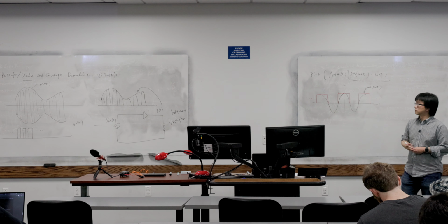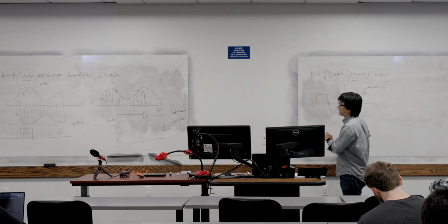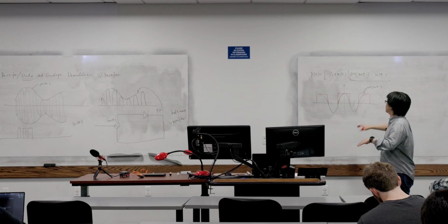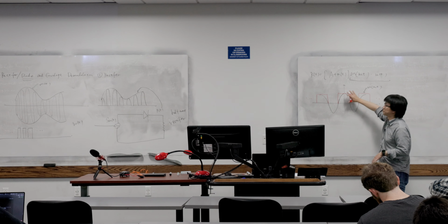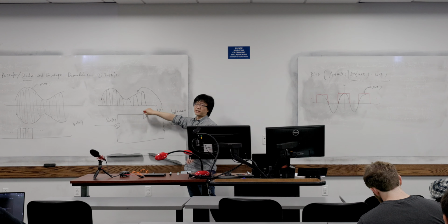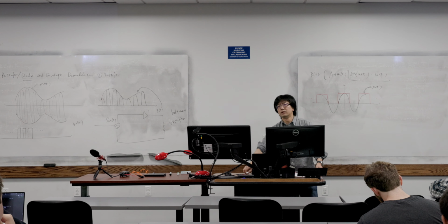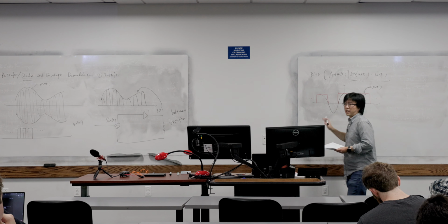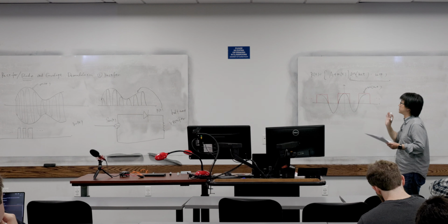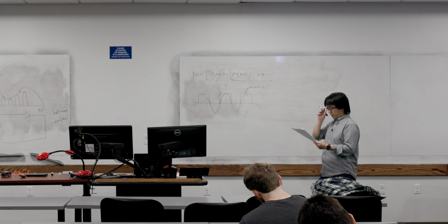Right, so this is what we do. Okay, this is what happened mathematically, right? In practice, it doesn't mean we multiply by the square waveform. In practice, what we do is just pass that through a diode. But here, it's easier for us to analyze and helps us design the decoding approach, the demodulation approach. Okay, great.